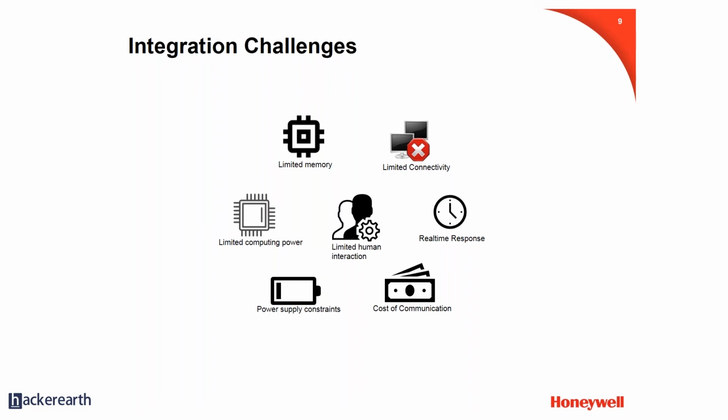You need a very good watchdog timer design that can monitor the state of your applications, realize that there is a deadlock or an out-of-ordinary condition, and then cause a reset, which allows the applications to come back to a state where they can continue to execute and perform the tasks they had to. So put together, these constraints make the edge device part of IoT very interesting and very challenging.